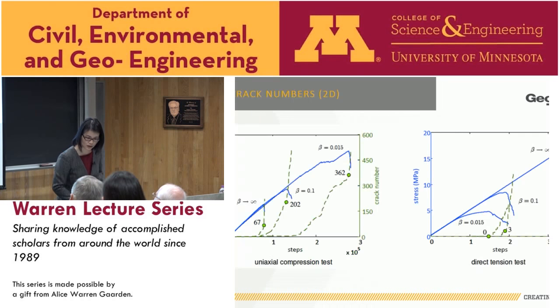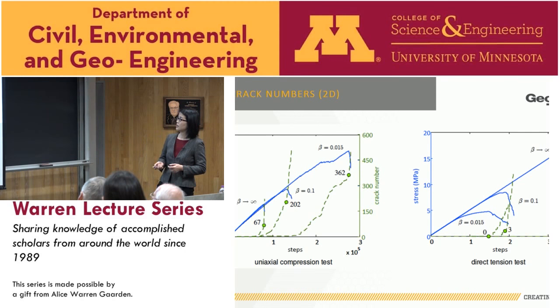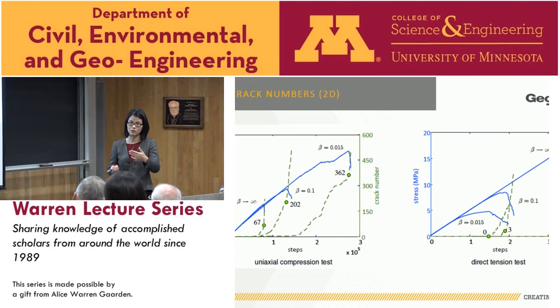And it could bring your strength ratio to quite realistic numbers. And as I said, a little bit of explanation is needed to understand why, with what we prescribed, the bond strength increases with beta, but the compressive strength actually decreases. So if you look at the micro crack number, if a bond breaks, we refer to that as a micro crack event.